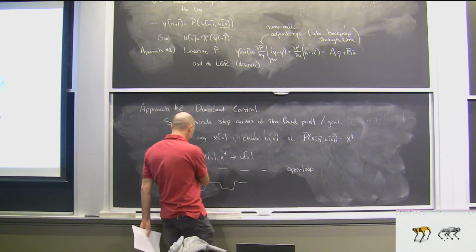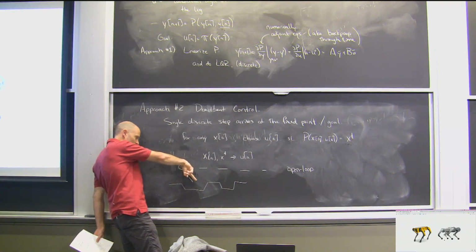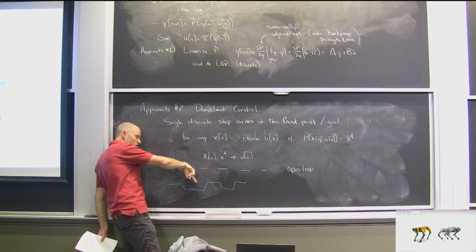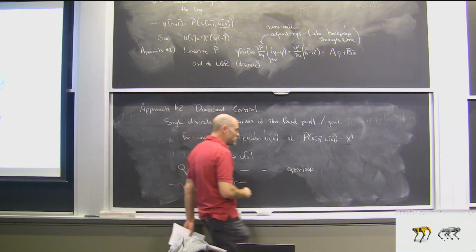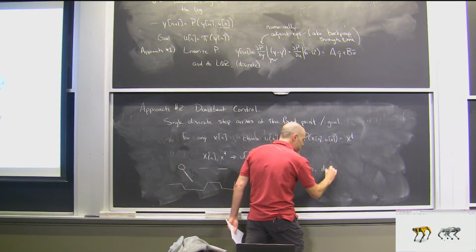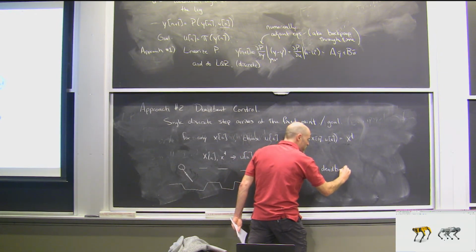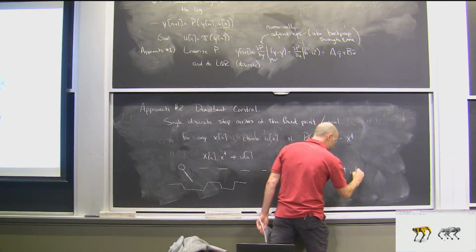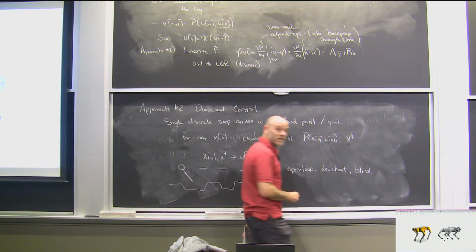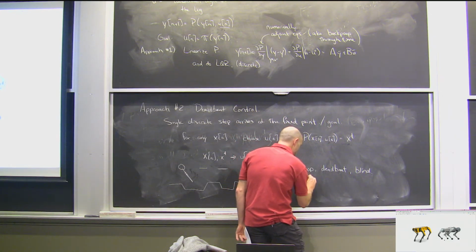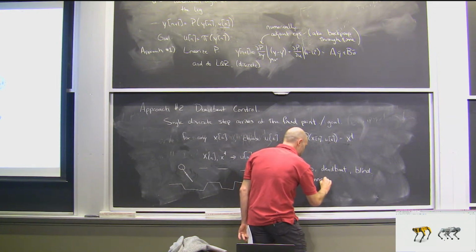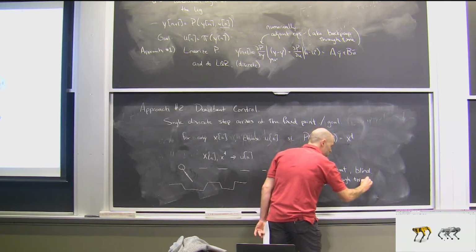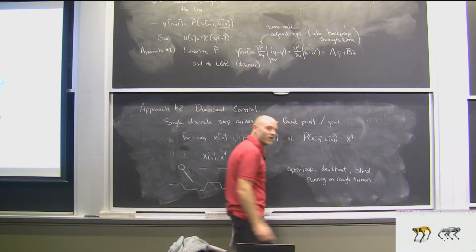Okay, it only depends on time. I can just have the time recorded since I left the apex, and I can just sweep my leg through a pre-observed schedule. Open loop, it's going to be deadbeat. Always gets me exactly back to the desired height. Blind, it doesn't observe the height of the terrain at all. Running on rough terrain, or uneven terrain, if you will. Those words you wouldn't expect to be all in the same sentence.